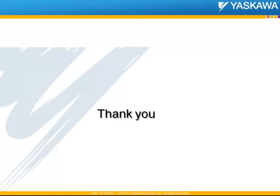There's a question concerning whether we can recommend any best practices for determining if an amplifier has been replaced with a new one. Yes, there is. If a new amplifier has been put in a machine, we could always use one of the function blocks that we talked about here. Y verify parameters does a check of the parameters that were stored on the controller relating to a particular axis against the parameters on the axes that are connected at that point in time.